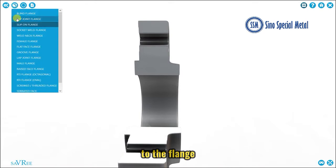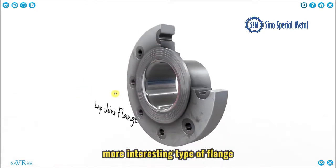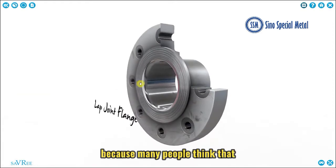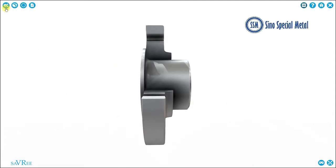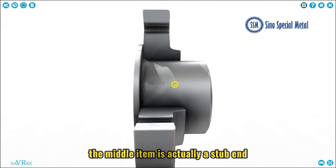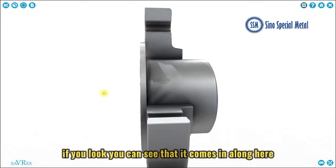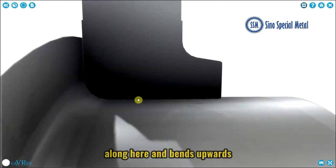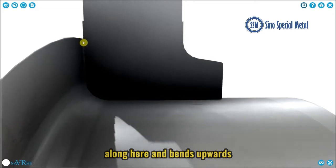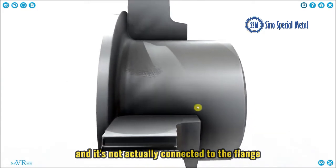The lap joint flange is a more interesting type of flange because many people think that this whole item is the lap joint flange, but they'd actually be wrong. The middle item is actually a stub end, which is a type of pipe fitting. If you look, you can see that it comes in along here, and bends upwards, comes across, and it's not actually connected to the flange.